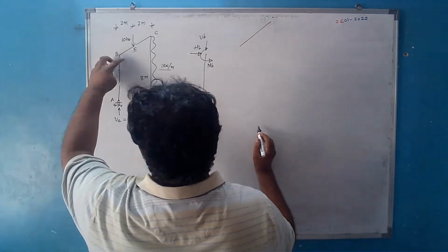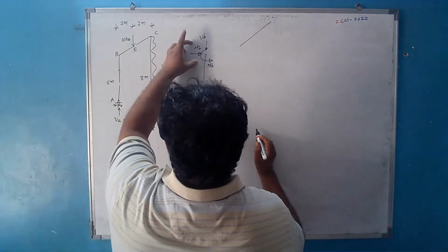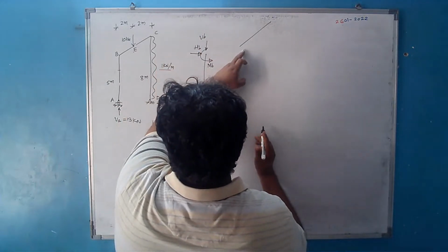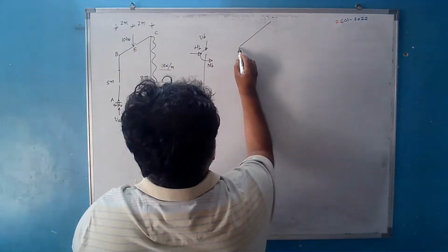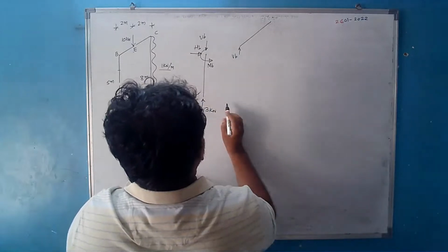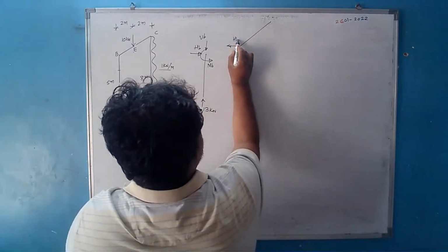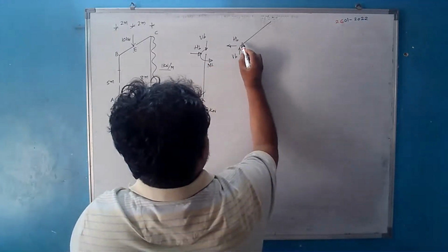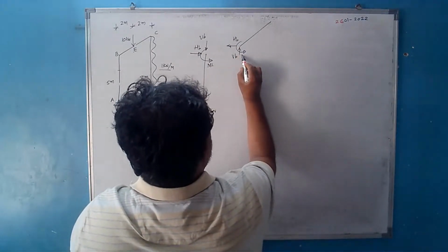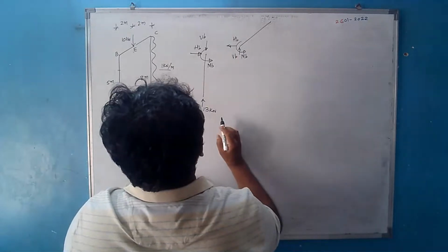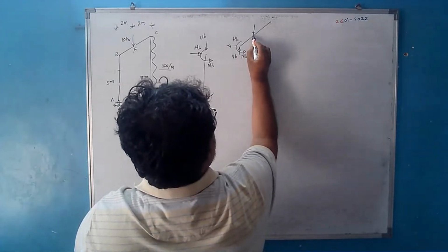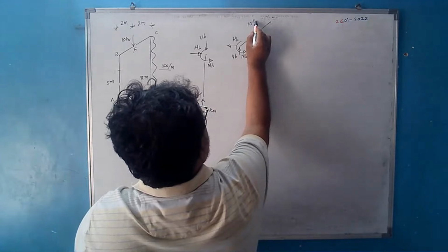For this inclined member at joint B, whatever I had considered for the vertical member, I have to consider the opposite. So here I will consider VB. HB was considered right, so it has to be considered left. The moment MB was considered anti-clockwise, so here I have to consider the moment clockwise. There is a force acting here, 10 kilonewton.